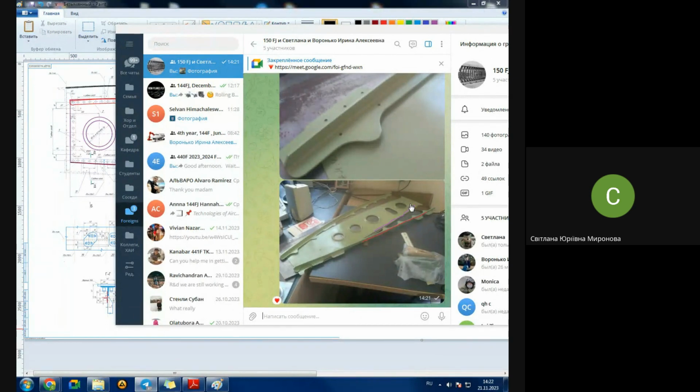You need to produce 100 airplanes. Each airplane has such a rib, so you may say that one rib takes only 1/100th of the jig cost. In case you're going to produce a couple of airplanes or one airplane, of course it would be too costly if for each singular rib you are going to make a special jig.